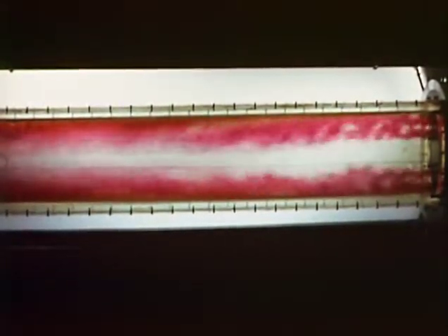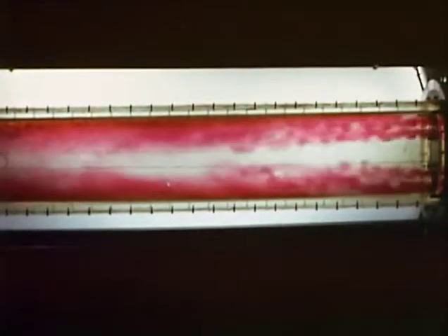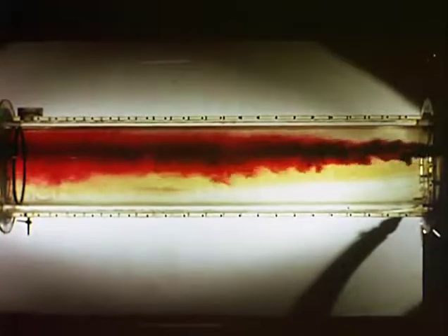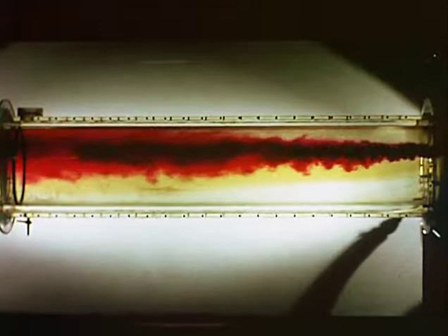Four injector nozzles extending 3/4 of an inch into the pipe are in use. The view is horizontal and the pipe velocity is 10 feet per second. 2 nozzles are 52 degrees above and 2 are 22 degrees below the horizontal diameter. 2 nozzles 30 degrees above the horizontal diameter were tested for the same flow conditions. Observe the large area of zero concentration in the lower half of the pipe.